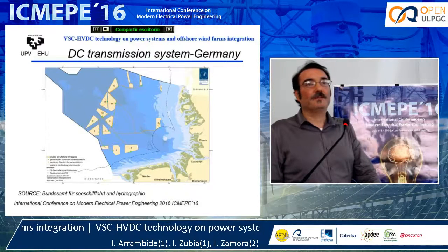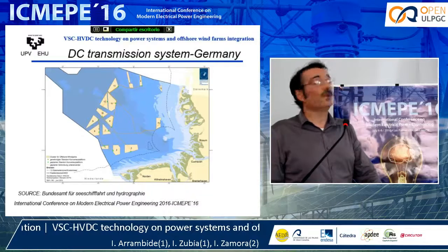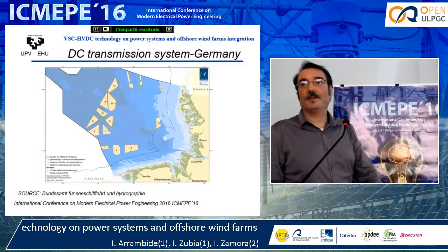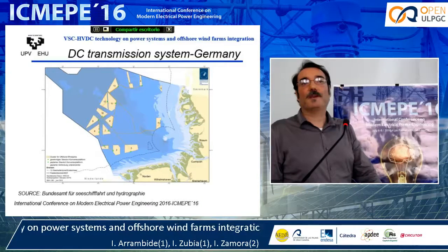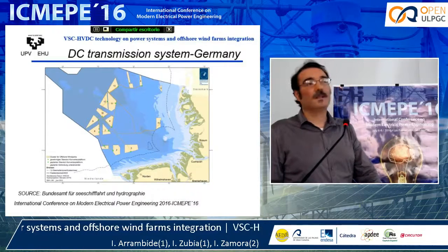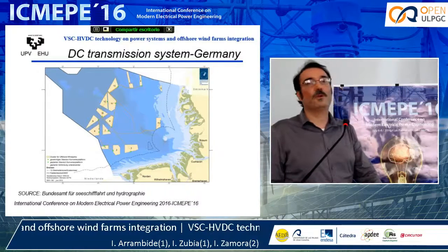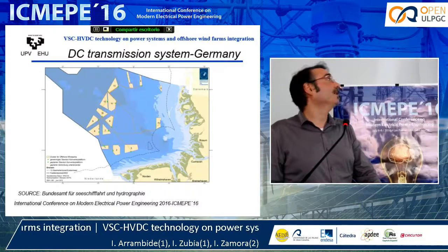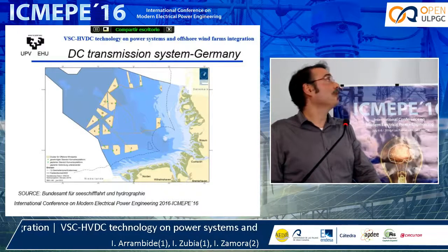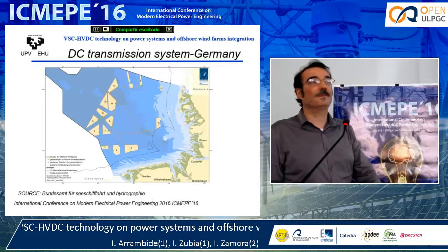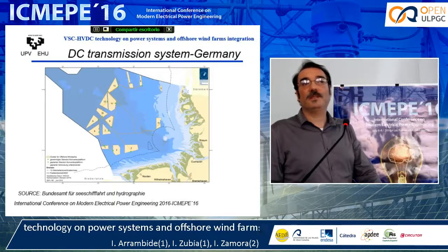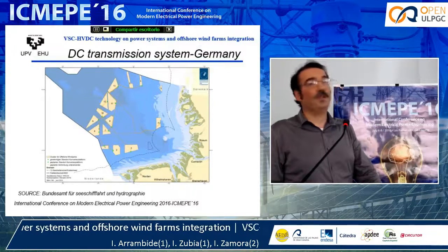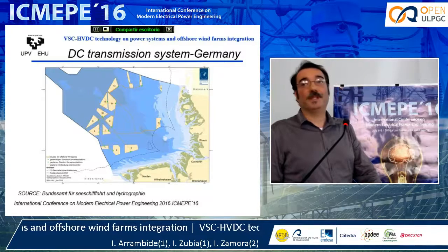Finally, it makes no sense to connect offshore wind farms in clusters or groups to the same direct current transmission system. If a cable fails, it makes no sense to lose the power of 2 or 3 offshore wind farms. So in Germany, they are considering, for next year, connecting different converter systems in transmission DC grids in the North Sea to achieve very good redundancy.